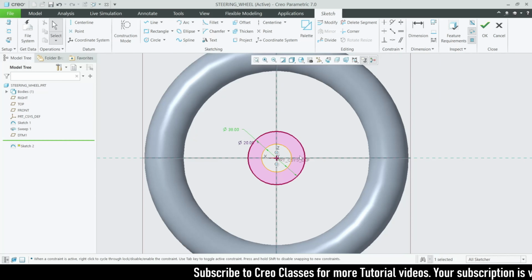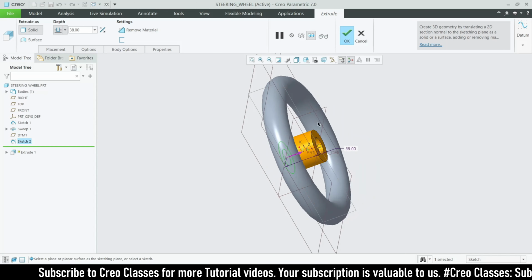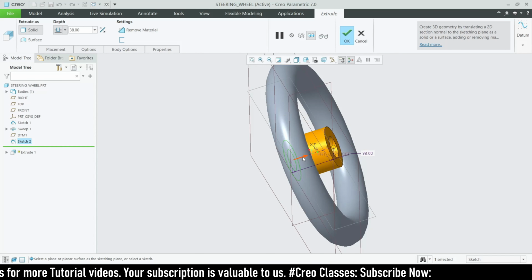Okay, we have created these circle parts. I'm going to click on OK, and I'm going for the extrude again. So here, as you can see, it is not a symmetric extrude. It will take as a blind extrude on the top surface.